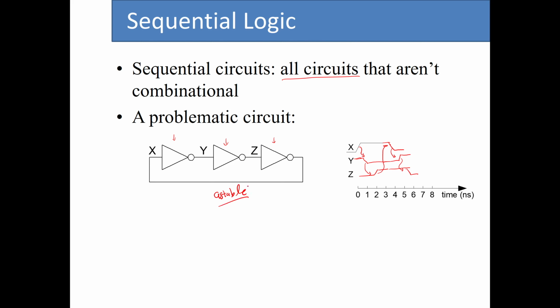If you remember, when we were talking about the bistable circuit, we only had two inverters connected back to back. And we said that because of this design, in whichever of the two possible states this circuit is, it remains in that state indefinitely. But here, since we have three inverters back to back, we don't have a stable state. In fact, our circuit is astable.